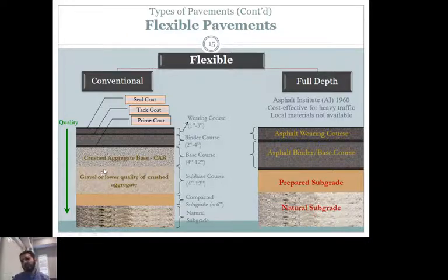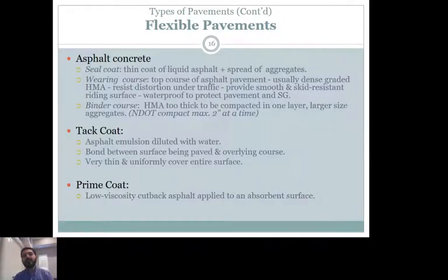So if you're designing 6 inches, you're gonna come 3 times, 3 days. You're gonna apply the first layer 2 inches, compact it, and come second day, apply another lift, and third day the third lift to achieve the overall thickness.